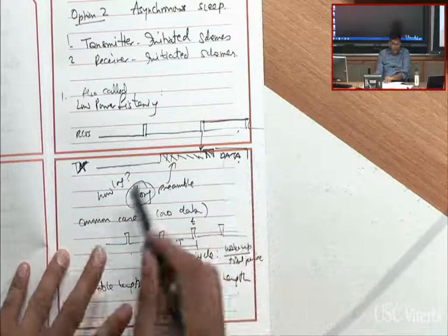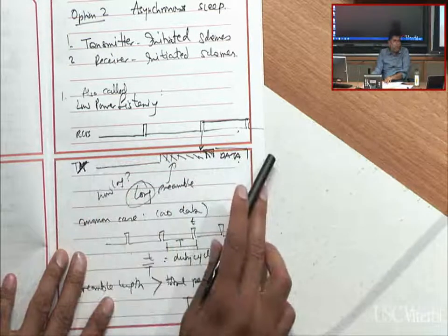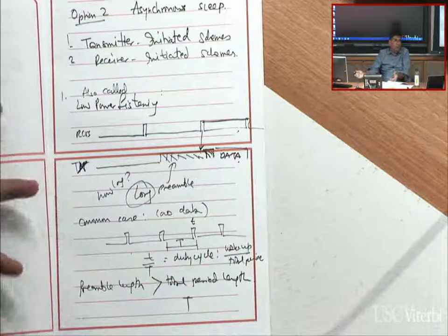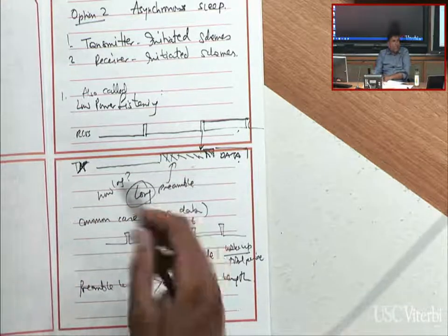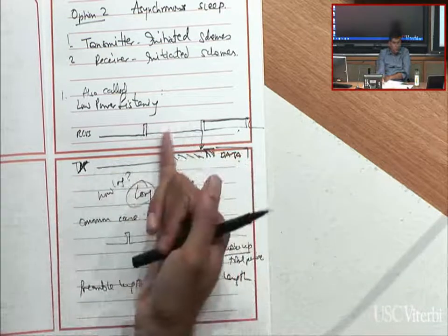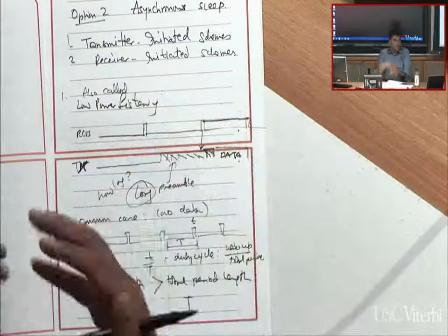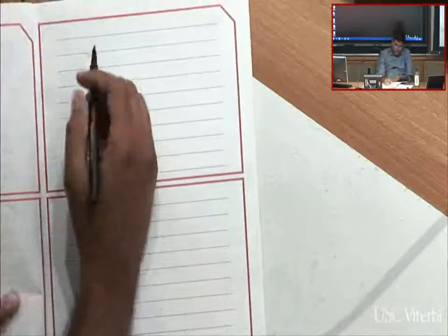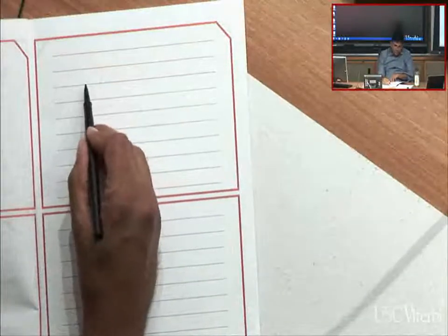The benefit of this approach is that the receiver most of the time will guarantee very low energy usage. And it's transmitter-initiated because it's only when the transmitter has data that the whole wake-up happens at the transmitter, the receiver is woken up, and data is communicated to it. So that's the sense in which it's transmitter-initiated. The opposite scheme, called receiver-initiated, would do the opposite.